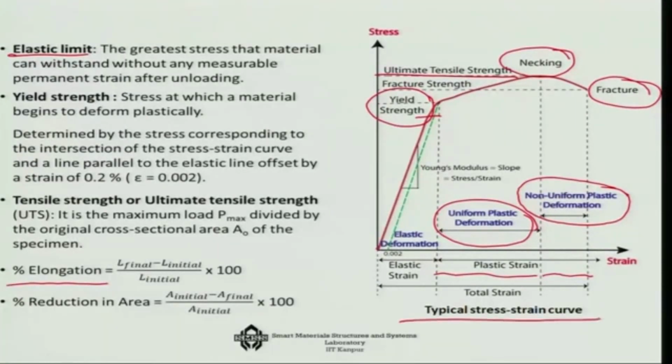So, this is a typical stress strain curve for a ductile material. How will it look for a brittle material? I can draw it qualitatively here, where stress is denoted by sigma and strain by epsilon. If I draw sigma versus epsilon for a brittle material, it is just one single line, maybe with some point of nonlinearity, and then it sharply fails. That means it will not show any plastic strain or plastic deformation. That generally happens in brittle materials.